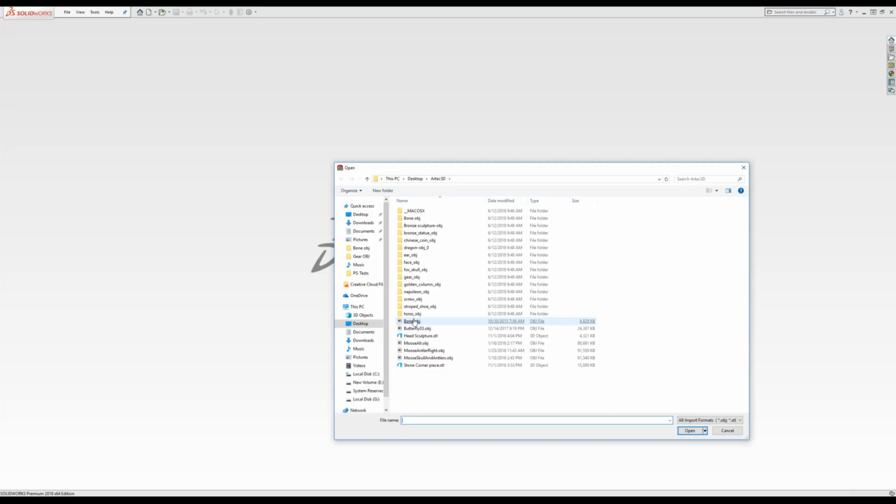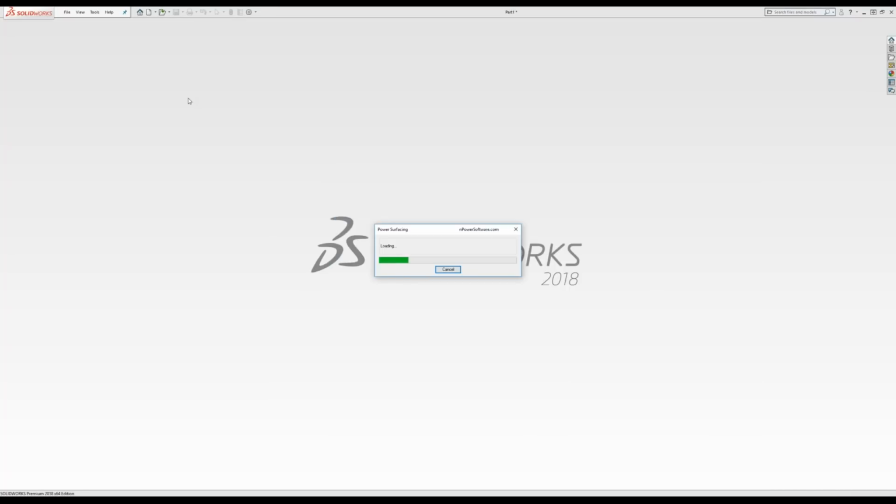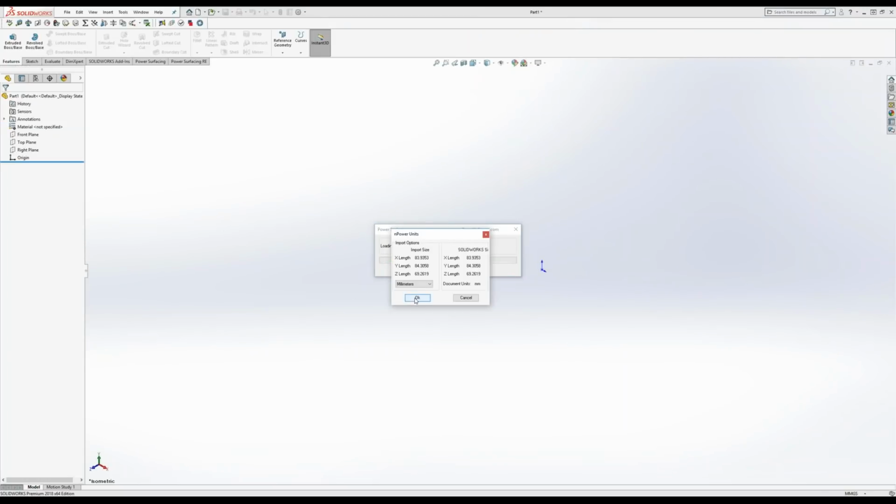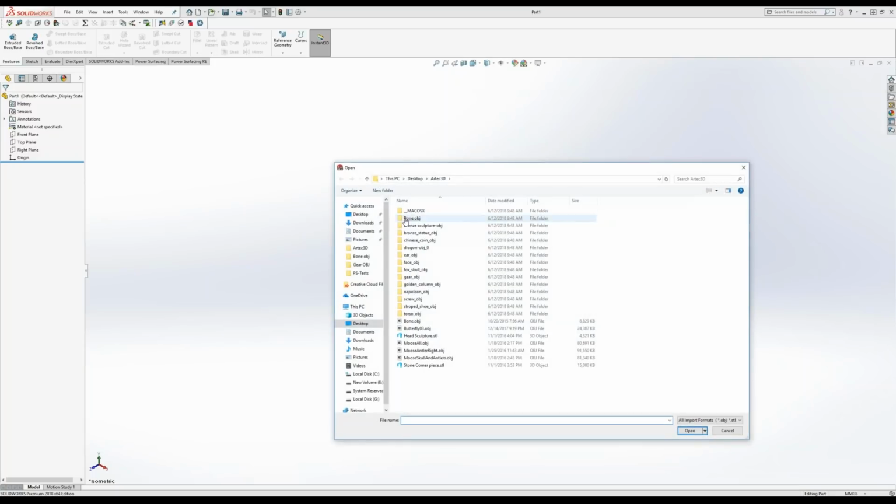The other interesting thing is that we do have an offset tool inside of our software that will allow you to offset the original surface and create another body, and that will be an offset of that. And if, for example, there are self-intersection areas, you can use our tools to check that out and fix them. So there are ways to get around it if it doesn't work. It really depends on the level of surface detail, and it's just like any SolidWorks surface in that respect. Thank you, Gary. That works for us. If you have further questions, type them in and we'll address them after this section. So stick around.